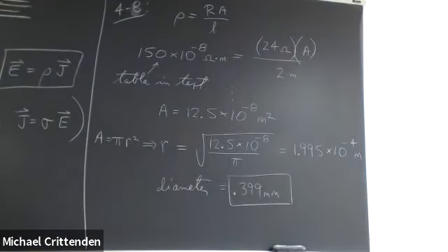If the radius is 0.1995 millimeter times 2, for all practical purposes, 4/10 of a millimeter. Whatever wire gauge is closest to that is what you would want to make this toaster oven work the way you want it to work.